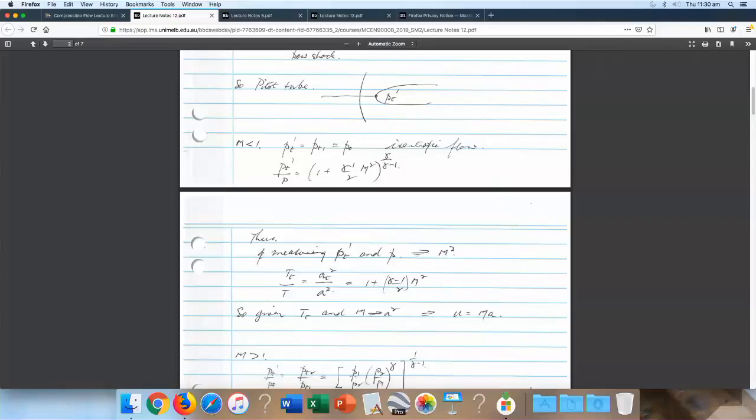I had the flow at an angle beta, and so I could always add this tangential velocity v for the oblique shock. So now this flow here, I have a shock wave that changes the total pressure. But from here on, the flow is regarded as isentropic.